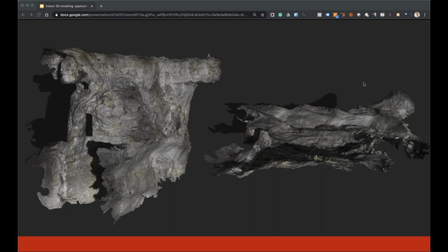But what's interesting to see on this model, here, what you see on this image, it's very difficult to see, but there is what we call overbreak. So overbreak is exceeding material that fell into the cavity, and which is diluting the ore that is extracted by the miners. And this is actually changing the quality of the material. And without a 3D model, it's quite hard to see how much overbreak is happening, and if there is overbreak happening.